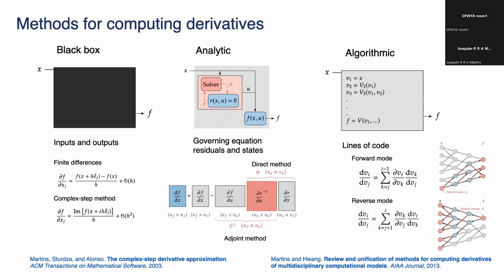So you saw previously, I have hundreds of design variables, all these twists, all these points moving around, right? So it's not feasible to perturb each one, recompute the CFD, do the difference for 1,000 times. It's just not possible, okay? So we need to be smarter. How do we get smarter? Well, we need to look inside the box, okay?